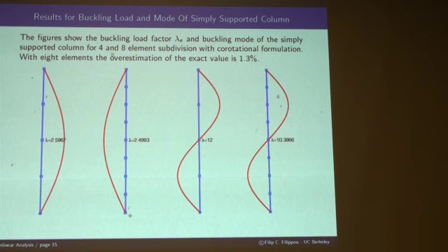All right, so if you wanted to represent buckling of elements, whether they are linear, like in this case, or nonlinear, it behooves you to have at least one intermediate node so that you can capture the rotation of the chord. That's if the top and bottom of the column are braced. If the top and the bottom of the column are unbraced, so the top displaces relative to the bottom, even without subdivision, you get a pretty good answer because the chord is already rotating, right?